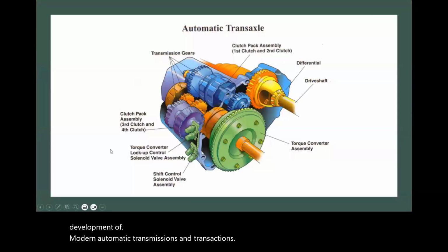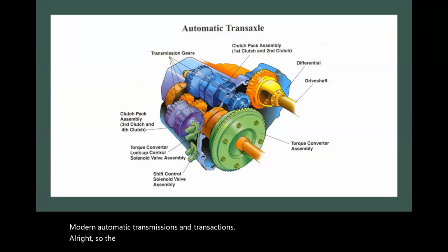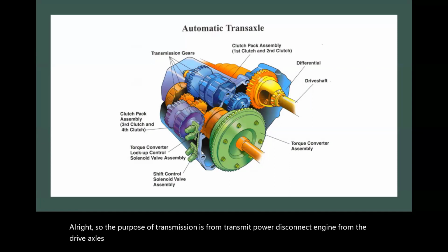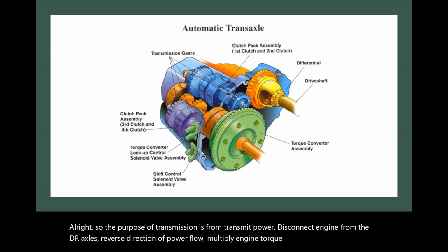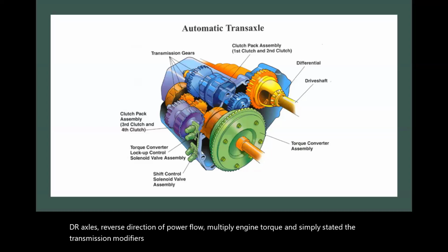All right, so the purpose of a transmission is to transmit power, disconnect the engine from the drive axles, reverse direction of power flow, multiply engine torque, and simply stated, the transmission modifies engine torque and speed to match the vehicle needs.